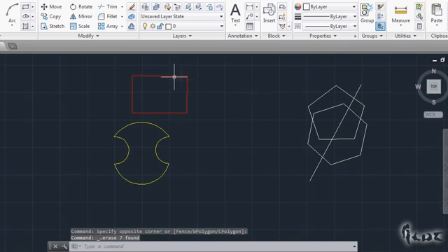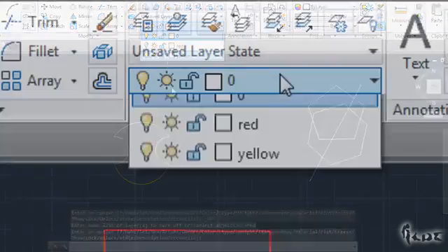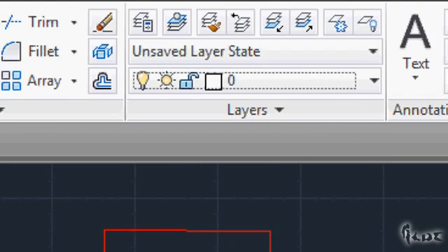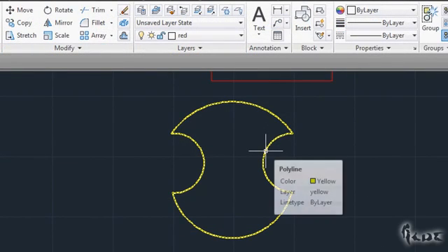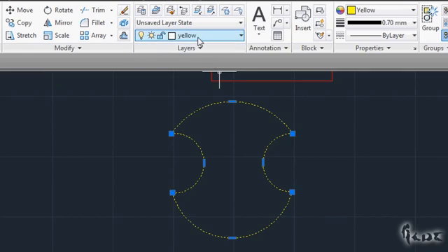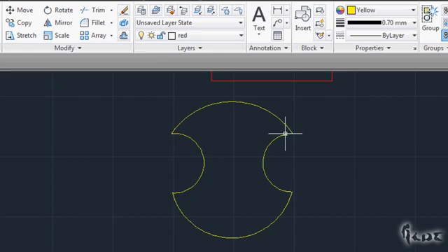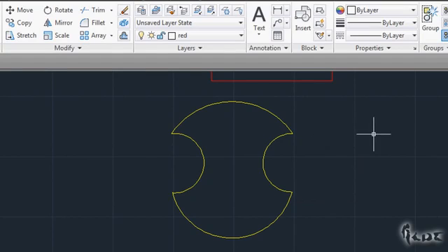You can see this effect also in the third space in the section Layers, next to the colored small square. By clicking on it, you can further check the full list of layers you actually have. And the 01 is the one you have by default. In case you want to add new objects to your newest layer, just select them and click on the slot before. Then choose in the list the layer with the name of the newest one. In this case, you won't have any extra copy, since you are just moving an object between two layers.